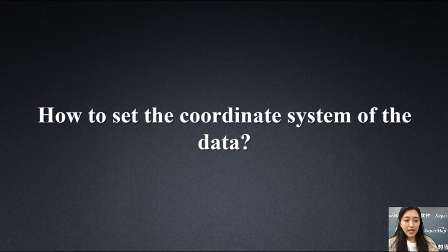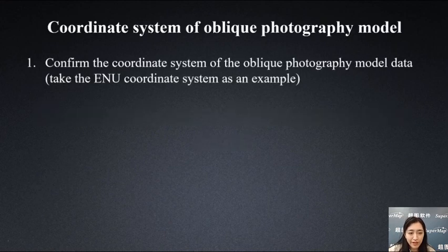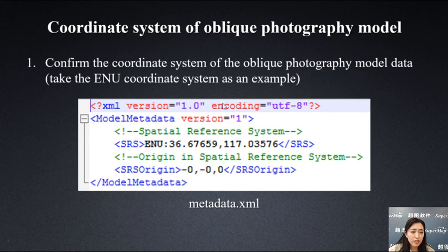Let's look at how to set the coordinate system of the oblique photography data. Do you remember the ENU coordinate system? We should confirm the coordinate system of the oblique photography model data, using the metadata.xml if you have it.